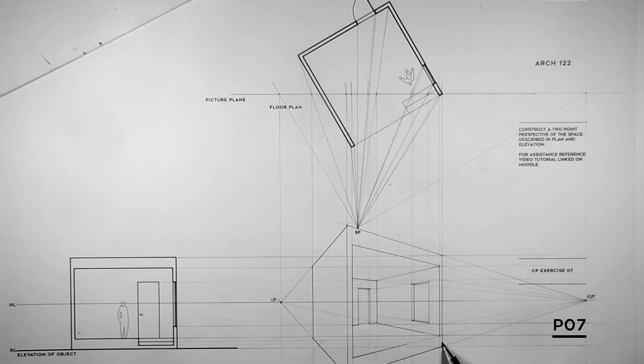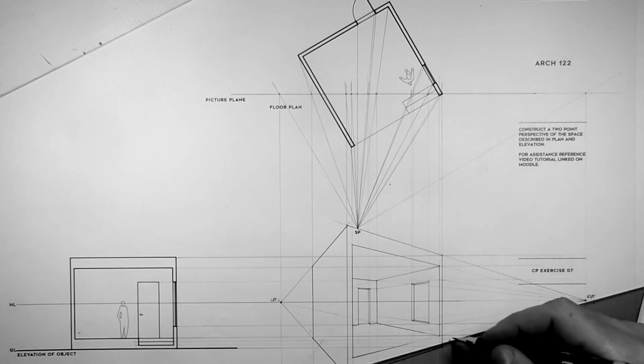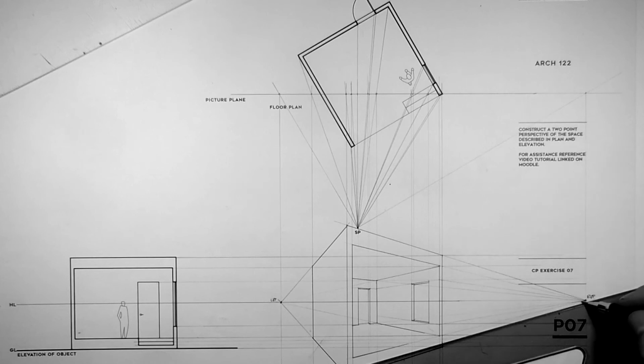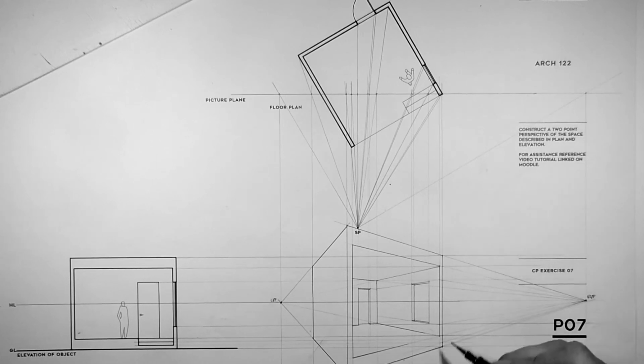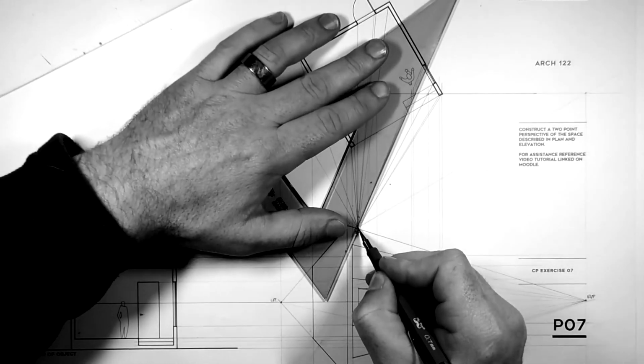So we have this lower step projected over to that intersection right there. I'm going to start from the right-hand vanishing point. I'm going to go through that point to define the lower edge of the step. And so that intersection will be right about there. And then we need to figure out where it ends over here.